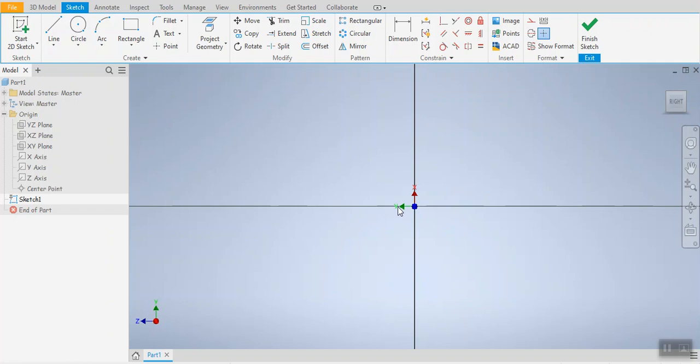How do we create a sphere in Inventor? It was easy in AutoCAD. You go to primitives, but no, in Inventor you have to generate a line as long as the diameter first. So start from this point. What is the diameter of the sphere? A quarter of an inch, 0.25. I'm typing this number now and enter, and the line is created. Good. I'm hitting the escape key.